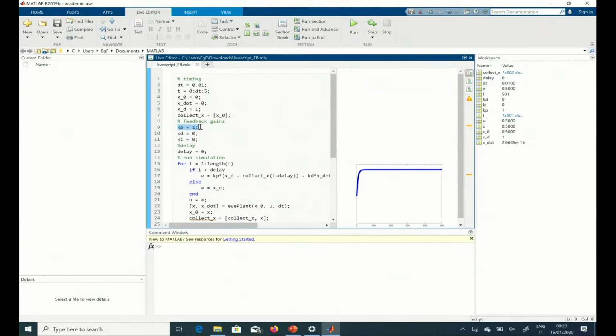proportional controller, where we start with a gain of 1 here, and we have no delay. We see that the system is stable, can reach the position and keep it. But as soon as we increase the delay here, our system dynamics completely changes and starts to become more unstable. Of course, if we further increase it, the system becomes more oscillating, and for very high values, it becomes not controllable.